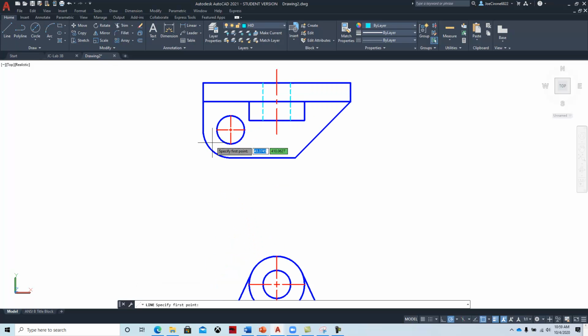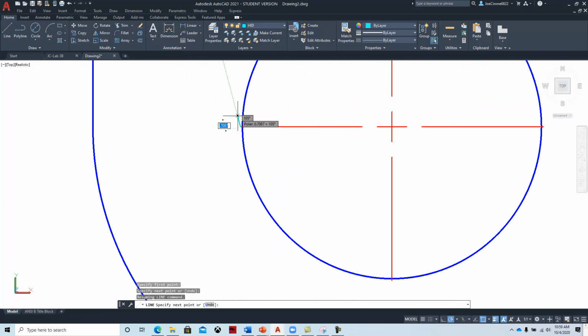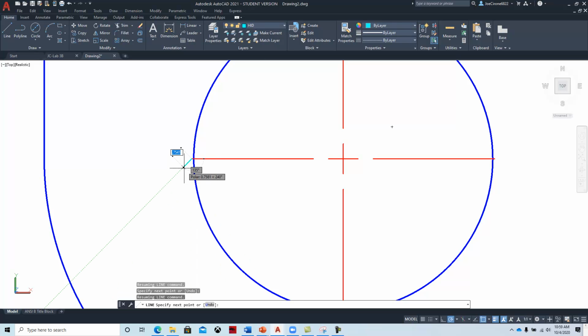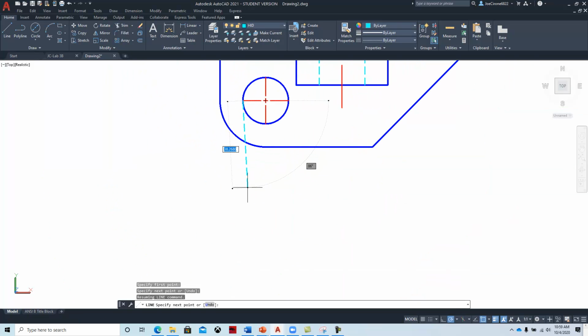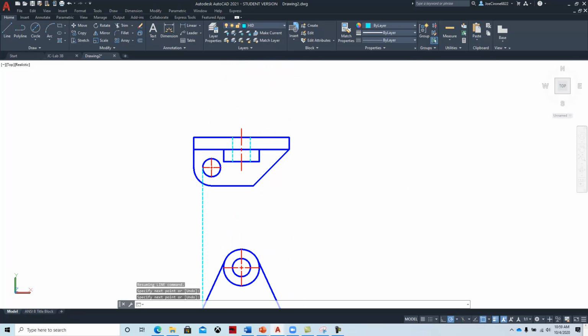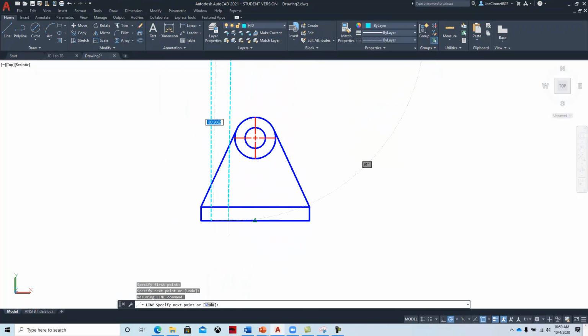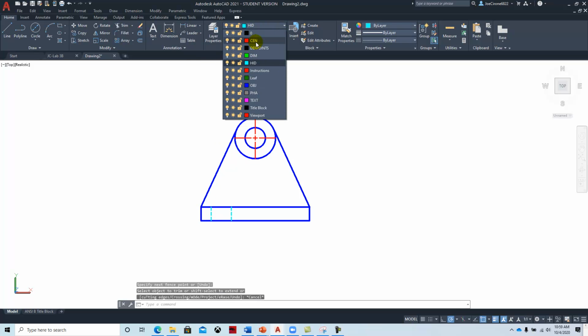And so you can see as you start to work these problems, what happens is that the geometry, and I almost grabbed the wrong part of it. I wanted the line from the quadrant, not from the endpoint. You can see it sticks out a little bit, just enough to make it inaccurate. Quadrant will grab the circular geometry. And then we'll project down the center line.